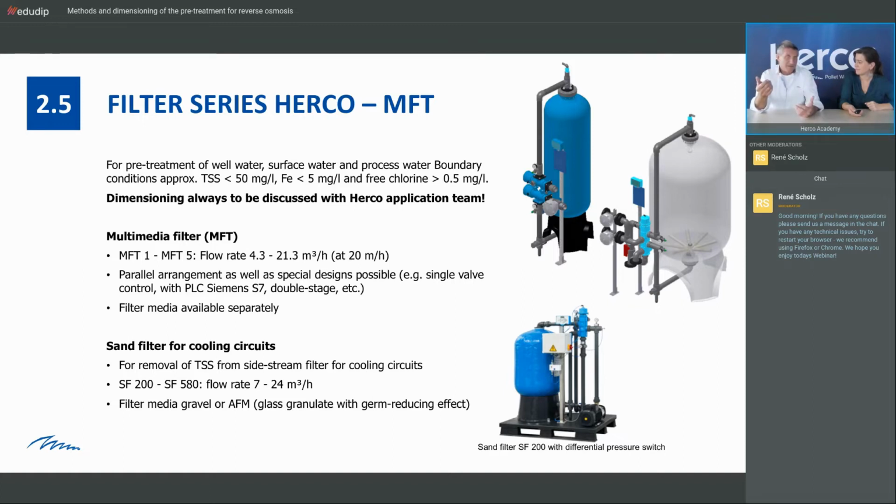And I think it needs to be backwashed then very often. So it needs to be backwashed because otherwise you have so much dirt in your system that you can't go on anymore. You would get a breakthrough anyway, or a pressure increase, and that's the reason why the system has to be backwashed very regularly, very often.